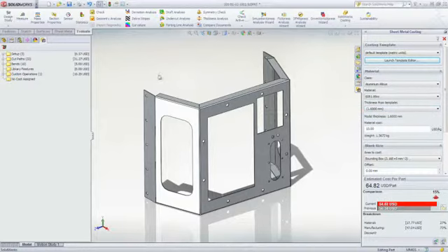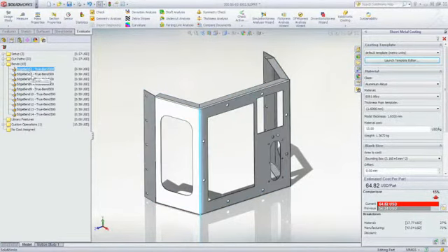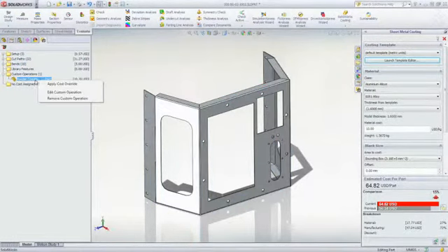The costing tool works by looking at the various part features and assigning these to specific manufacturing operations. For sheet metal, that means cuts, bends, and even custom tools or operations. If desired, you can even drill down to specific operations to see the time and cost associated with them. Custom operations can be automatically accounted for based on the template or manually applied as needed.